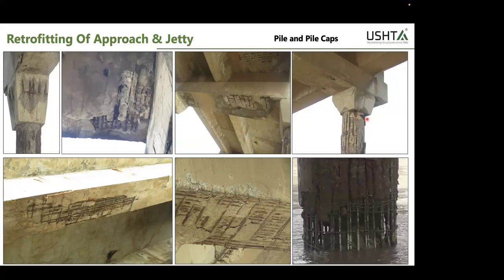And again, the piles which were repaired also failed. Here also you can see the corrosion. The cover here is maybe less than 20 mm, which is inappropriate for this kind of structure. You should have at least 75 mm of cover here. Similarly for the beams here. But in the pile, as I mentioned, the case was different. Above water, it was corrosion. In the splash zone, it was corrosion.